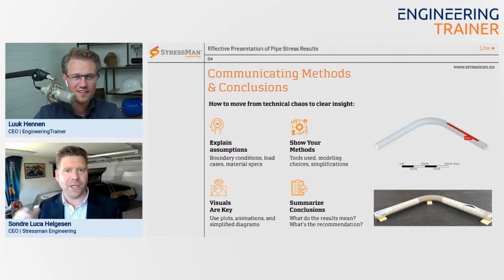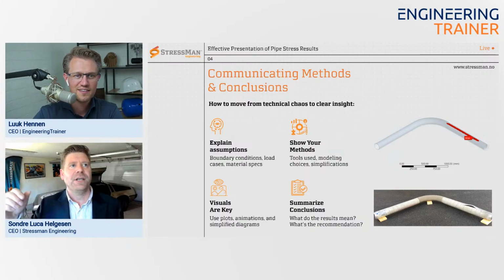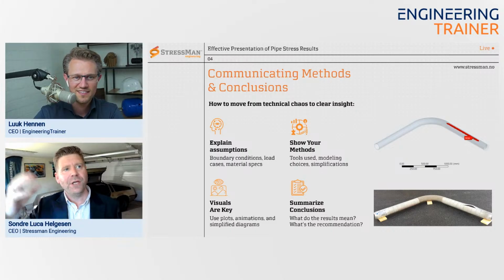So at least we had to break it down to make sure that we didn't combine all the deflections. This was structural deflections combined with thermal expansions. We didn't want to just slap them on top of each other and get away with maybe 50 cases, 60 cases, because then we would need to design much more complex expansion joints in this case. So here we condensed. We didn't condense. We expanded.